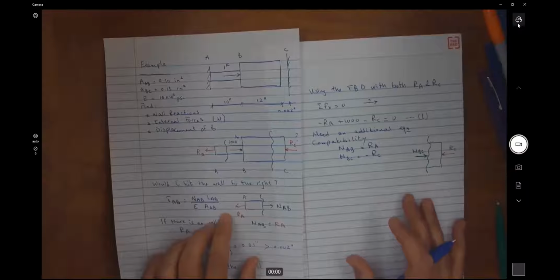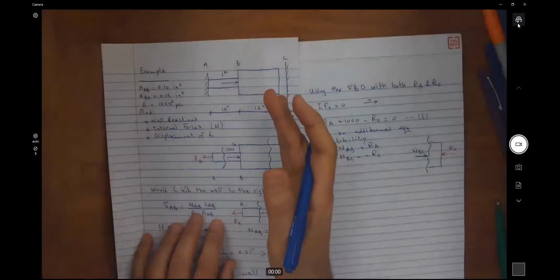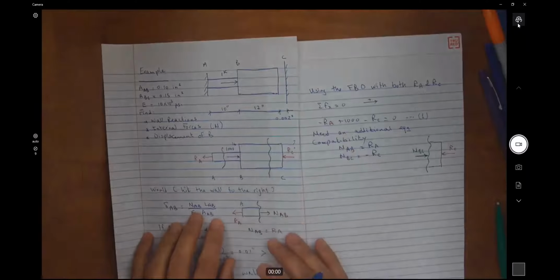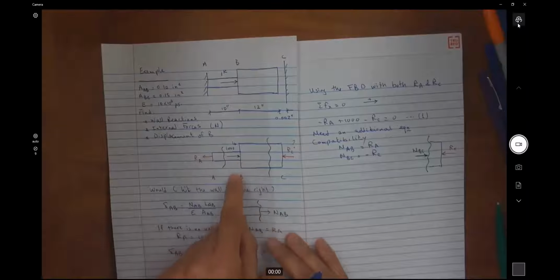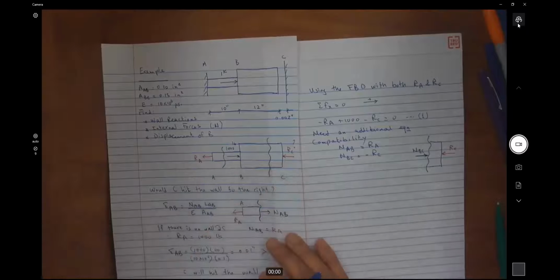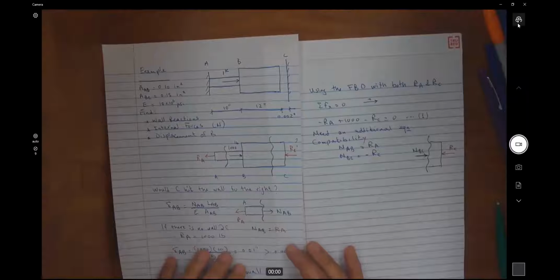Can you please repeat? No, you are correct, because I didn't say that very accurately. Point B needs to be at all times on AB and BC. And what I said would only be correct if there was no gap. But because there is a gap, a better way to say it is that when AB stretches and BC compresses, the total deformation or the total elongation can only be 0.002, correct? So yes, this is the better way to say it.